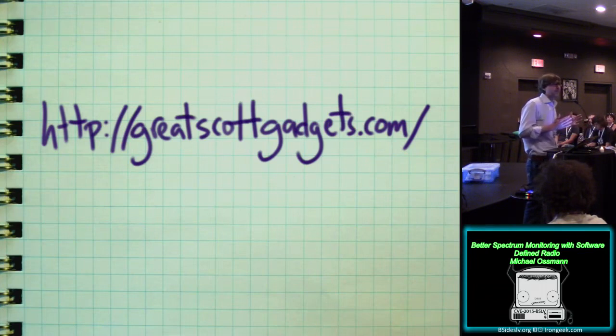So if you can have a set of antennas that are all used effectively, like if you're doing the array kind of stuff, an array of multiple receivers, and each one has its own antenna that's better for that particular frequency band, you might get much better performance. Also things to consider, like the polarization of the signal. Is it horizontally, vertically, circularly polarized? What direction is the signal coming from? There are all kinds of measurements we can make beyond just the stuff that I've been talking about. If we want to monitor spectrum on a large scale and observe how it's used, it might be nice to know where the signals are in addition to what they are as detected from a given point. So all those things can be accomplished theoretically with multi-antenna techniques, either by switching between antennas one at a time or by using many antennas simultaneously.